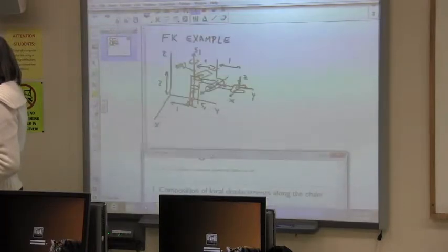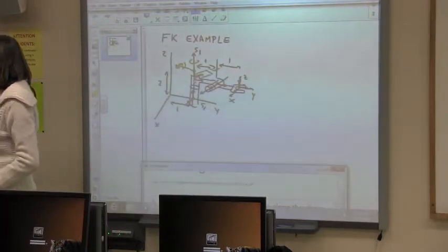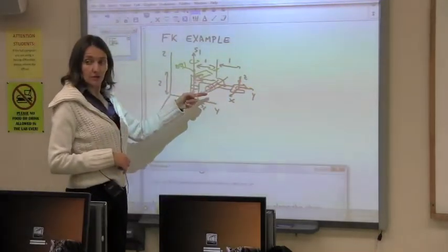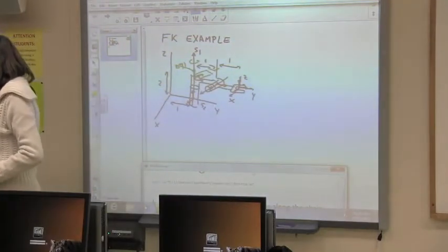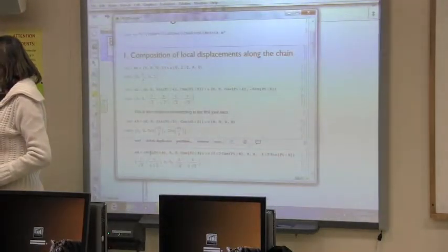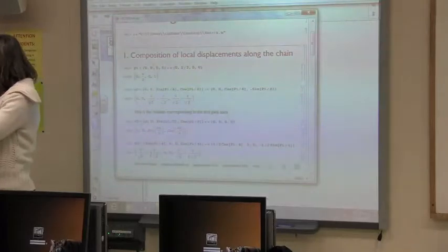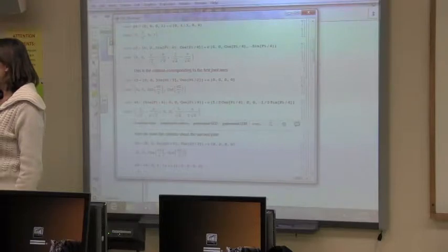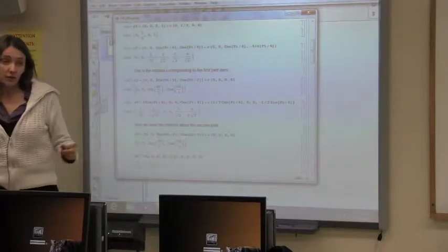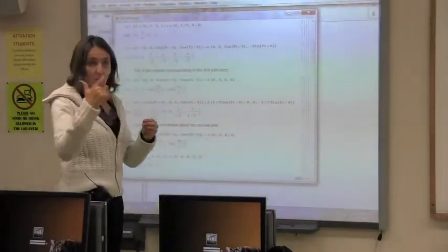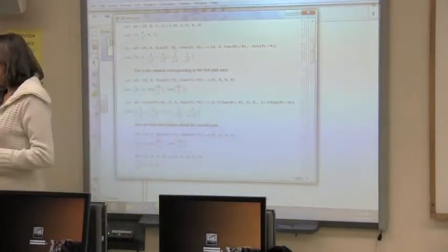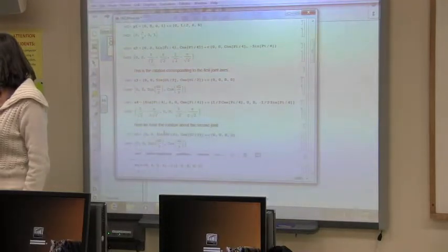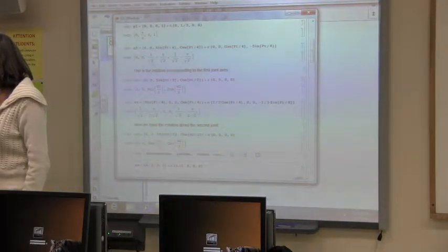Then we have, let me just imagine we haven't moved now. So we have this motion now along the x, and then we will have another joint rotation. Okay. So after this one, we have the motion, rotation and translation along and about and along the x-axis, and then we have the rotation of the second joint, which is a rotation of theta 2, but also about the z-axis, because the local z-axis is always coincident with the joint axis.